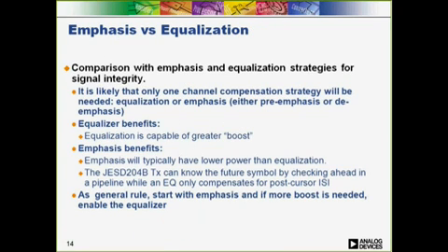The strategy for overcoming insertion loss created by ISI will depend on a few variables, but it is likely that, if compensation is needed, you will choose either emphasis on the transmit side or equalization on the receive side, but not both. There could be extreme cases where both are needed.